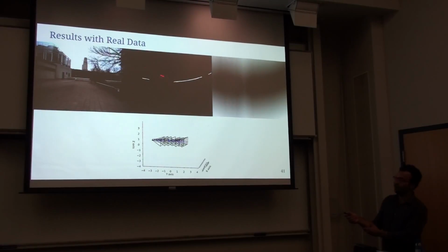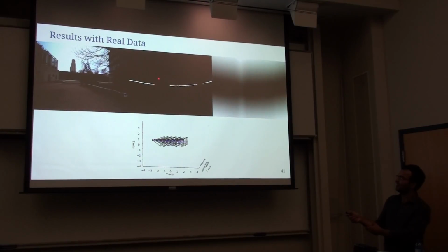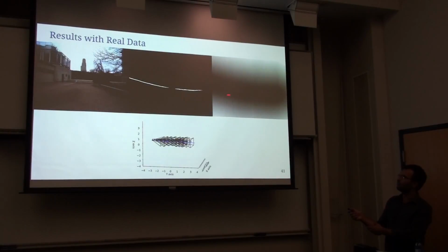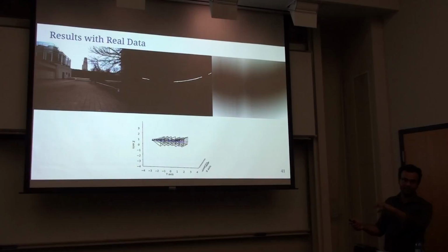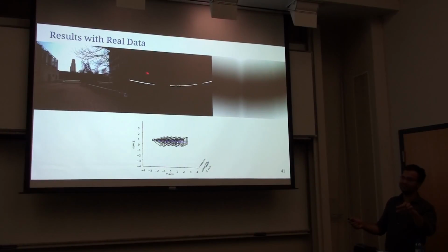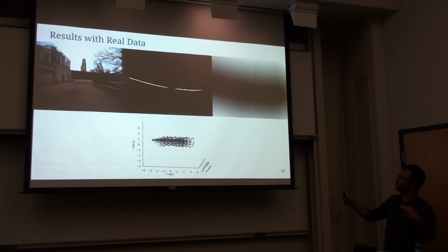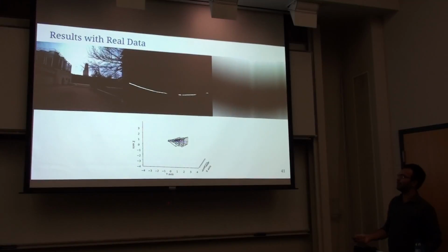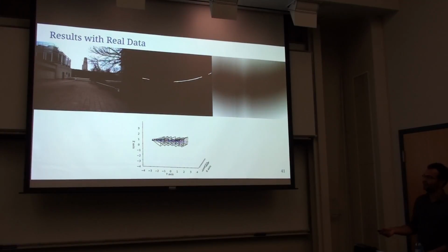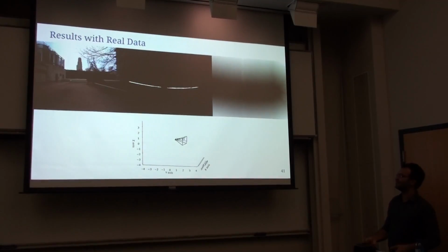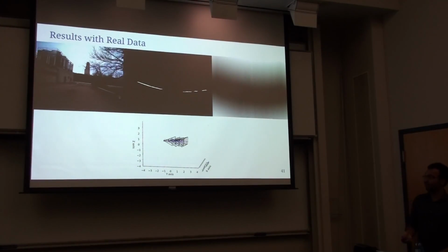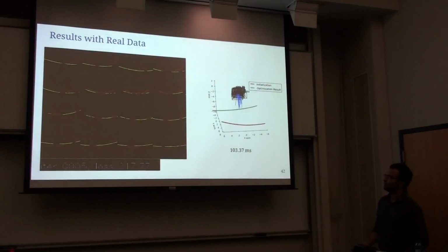You can see we have a lot of missed detections, and actually our objective function also kind of helps implicitly here, because the distance transform values along the curve are going to be lesser as compared to something here. So you can see we still have that pull towards the right answer, and there's the corresponding odometry. It's kind of like if you had been observing, it's like 8 steps back, 8 steps front almost. So this is how the results look.